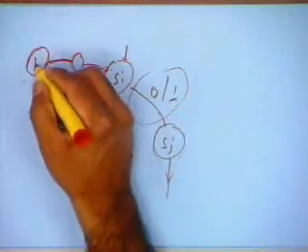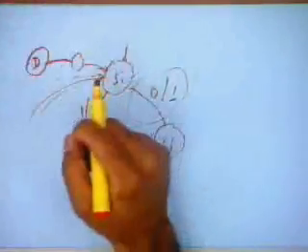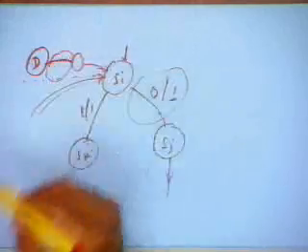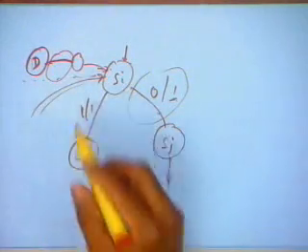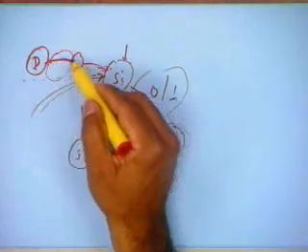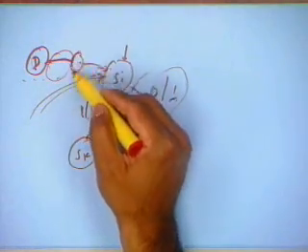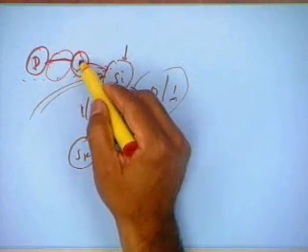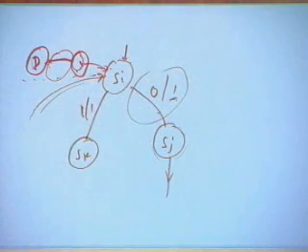For example, in this case, let us say this is state D as far as the previous sequence is concerned. Verify this particular transition. How do I verify this particular transition? I apply the homing sequence, reach D, apply the input required to perform the transition. I reach a final state over here, and now apply the distinguishing sequence here.